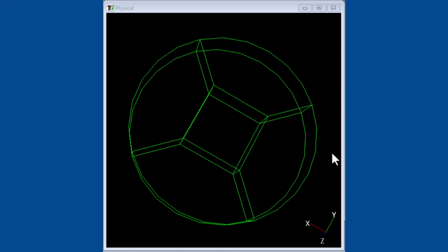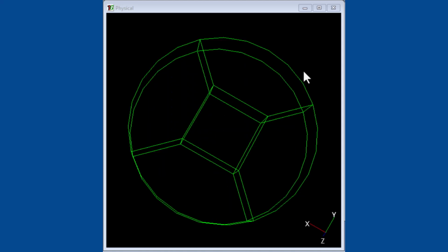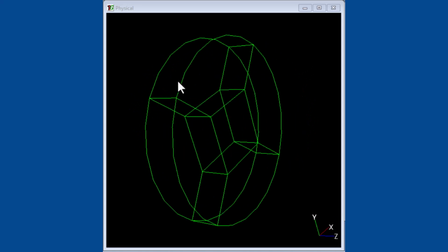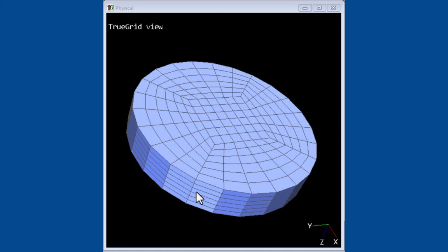However, with a few additional steps, we can improve the quality further. We are going to run this mesh through a smoothing algorithm that will shift the nodes to smooth and even out the element distortion throughout the entire mesh.